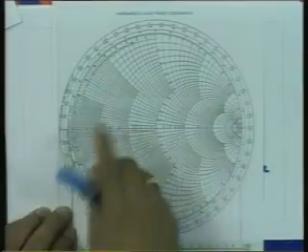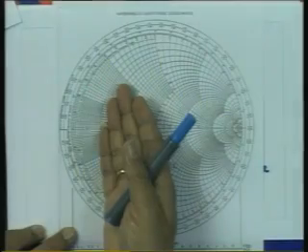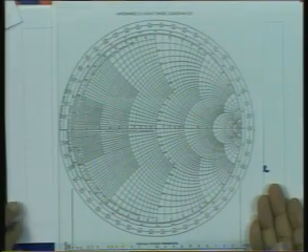Once I get that, I can do simple calculations of conversion from the reflection coefficient to the impedances or vice versa in a very simple manner. I can just mark a point of impedance on the Smith chart and then treat this as a complex gamma plane and find out the coordinates of that point, which will give me the complex reflection coefficient. So, the conversion of impedances to the complex reflection coefficient and vice versa has become extremely simple when the Smith chart is available to the user.